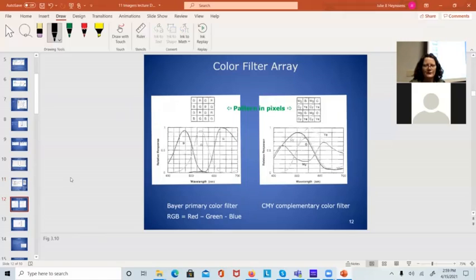This is how we get color images from basically just something that's measuring the amount of light at wavelengths less than 1.1 micrometers in the visible. We put a green filter, a red filter, a blue filter, a green, and we just interleave those, and we can do RGB, or you can use magenta.